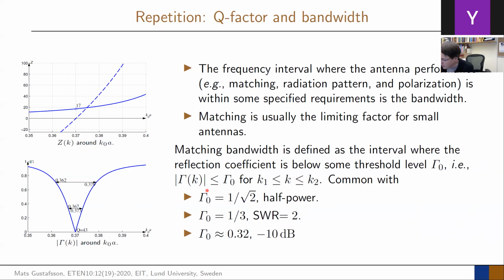So it comes down to this: you have an impedance, for example, of your antenna. You have some resistive part here and you have some reactance coming up there. If you then match it at its resonance frequency, you get a perfect match that goes down here. And of course, the bandwidth will depend on where I put the threshold levels. The Q factor is used to give them a common ground. It just talks about the generic type of bandwidth that I can get out of this.